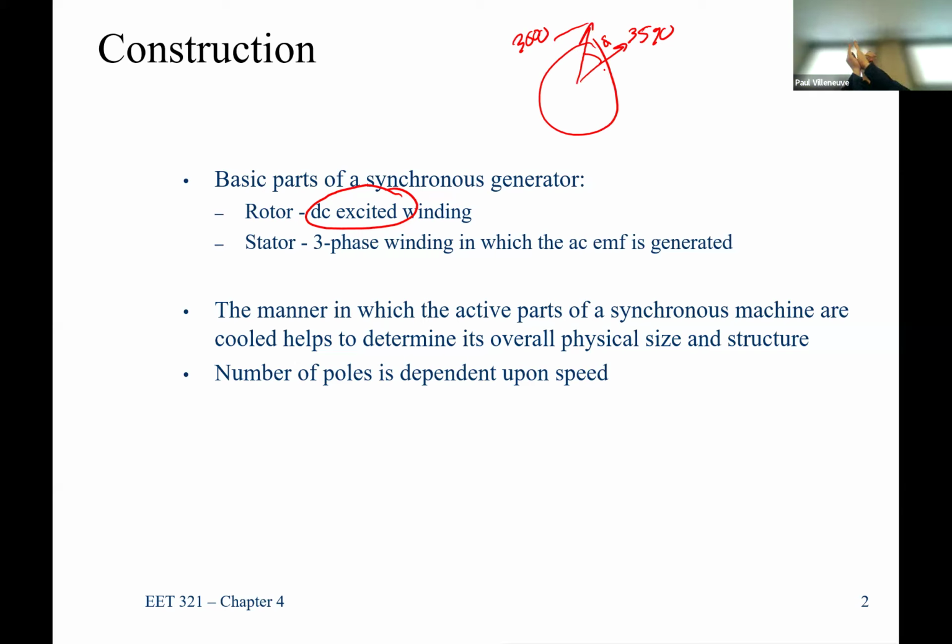So what does that mean? It tries to put out more torque. So it's going to have more power going out until it gets to over here, then it slips a pole. It quickly snaps around and then lines back up again, and then it starts to slip again. So it doesn't induce a different frequency. It's connected at 60 hertz. So you're stuck at whatever the grid frequency is.